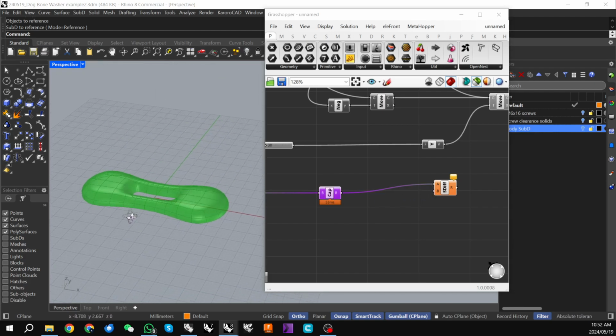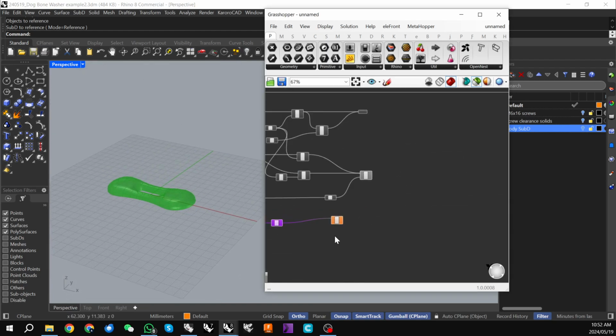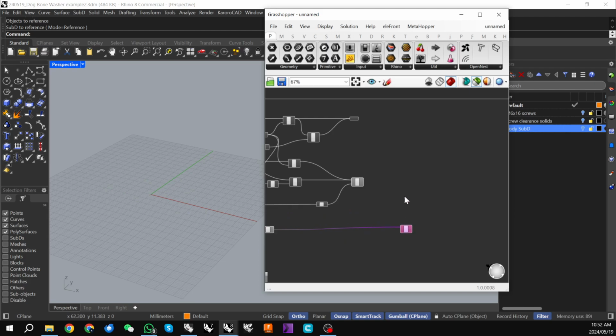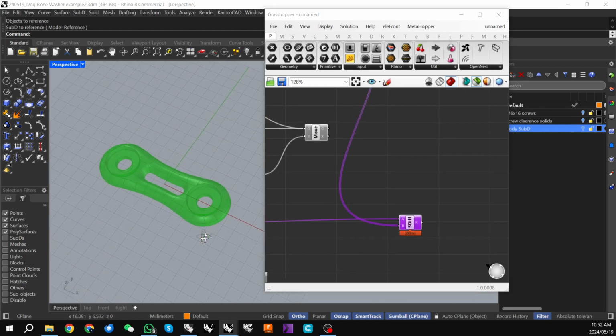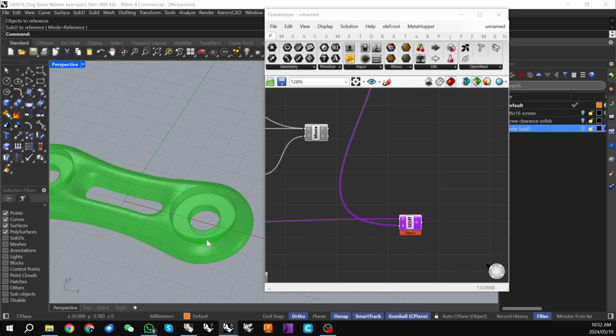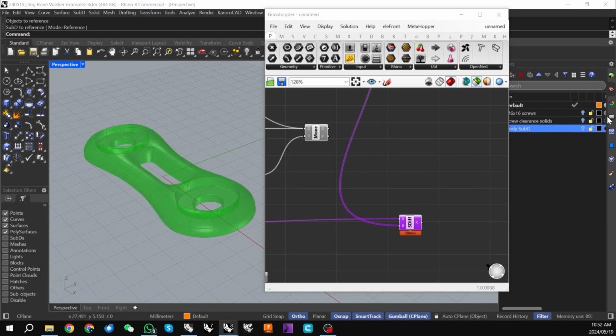For the solid difference, there is my capped sub D, which would actually be a B-rep now, and I can bring down these two clearance objects. The result of that operation is we now have our bolt mounting holes in this object.